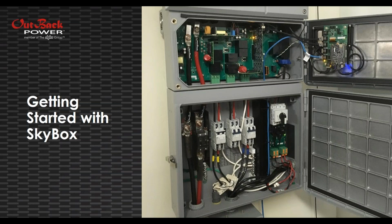So let's talk about getting started with SkyBox. This is a photo from another installation. And they've connected, in this case, battery over here in the middle of the picture, PV over on the right, and grid and load panel. And we'll talk more about this in a little bit of detail. Those CTs that they have in there are just for the purpose of, they were doing some initial early beta testing with us, so those are completely optional to install there. You would typically install your CTs out at the main so that you can move your point of measurement from SkyBox's grid port out to there.